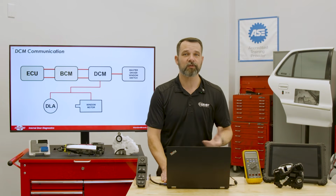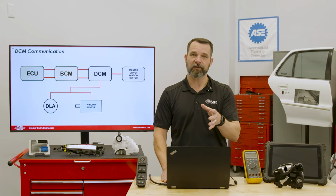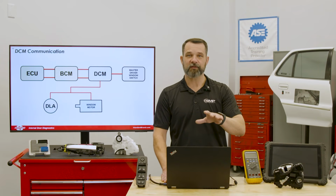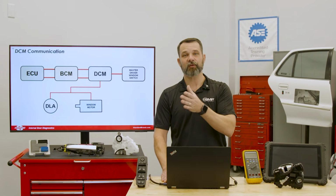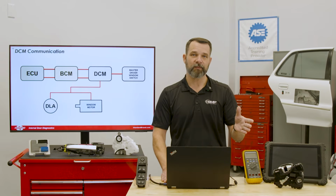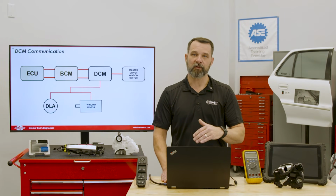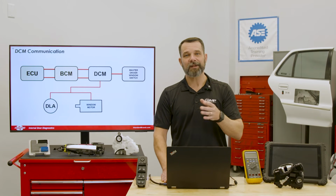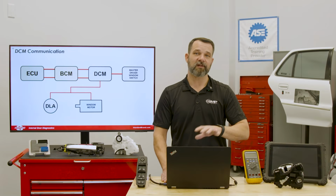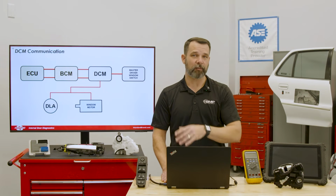So, all that said, how does the DCM communicate with the network? Well, it's very similar to our earlier example, right? The DCM communicates with the body control module, and in many systems, the master driver door switch communicates through the DCM and not directly to the BCM like before. The DCM sends the BCM status updates like lock and unlock request, window request, door ajar status, and then the BCM determines if an action is allowed and sends permissions or commands back to the DCM for operation.